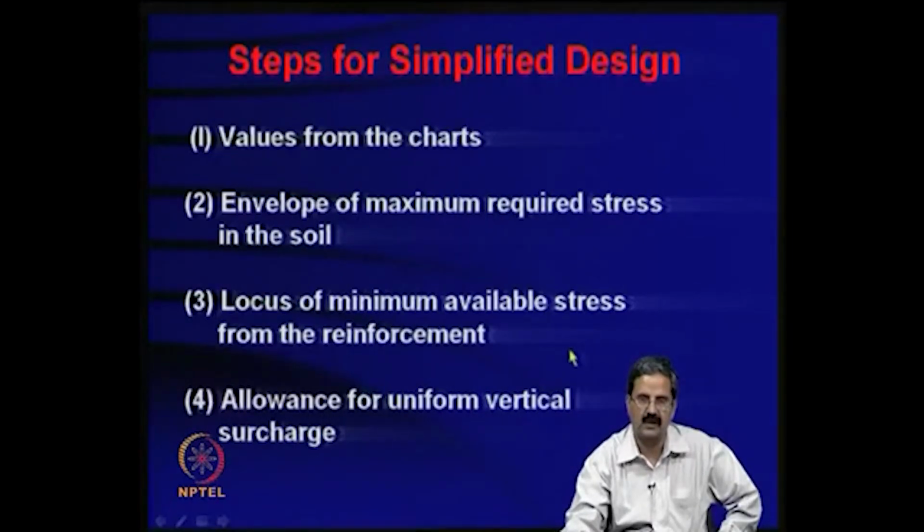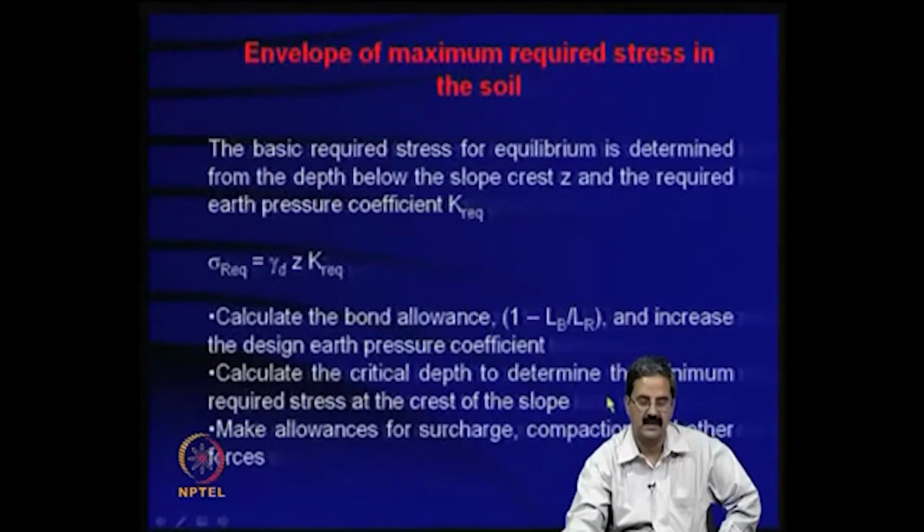Suppose the vertical slope has some traffic load at the top. How do you consider that in the design? That also should be addressed. We will see that. So, the first thing is the construction of the envelope of maximum required stress in the soil.